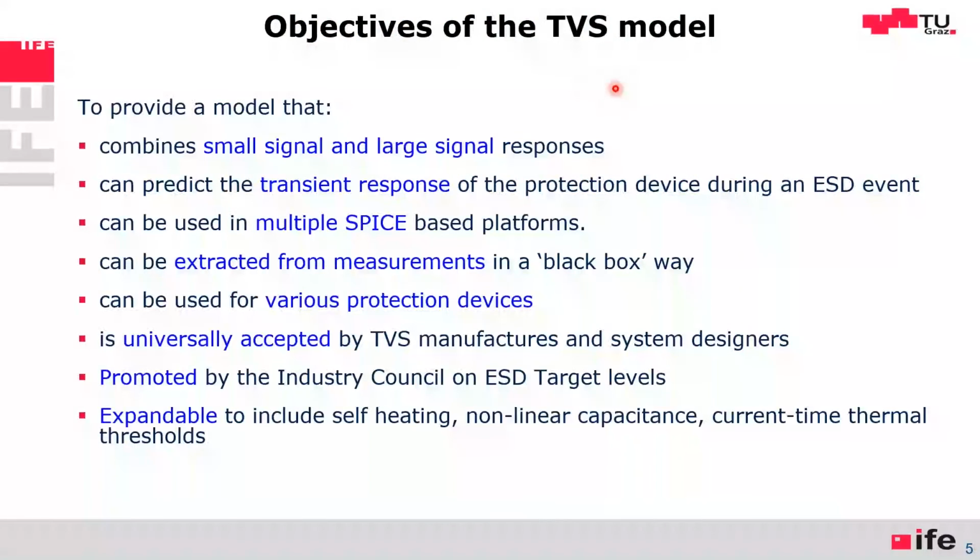Now, let's look at some modeling. So the consequence is we need to model the TVS, and we need to model it in many regards. And we also need models for the IC. This is sometimes a much more difficult problem to solve, but some manufacturers provide ESD relevant models for their critical IC IO pins like USB, etc.